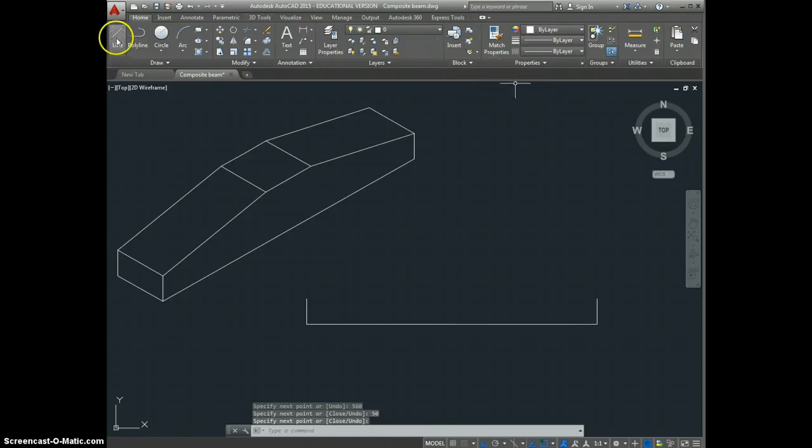So now draw a line from the midpoint, plumb up 100, enter, then move the mouse to the right 50, enter, and then what I'm going to do is pick on the endpoint, hit enter. So rather than redraw that line, I'm going to use one called mirror.